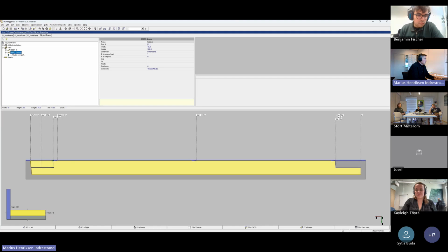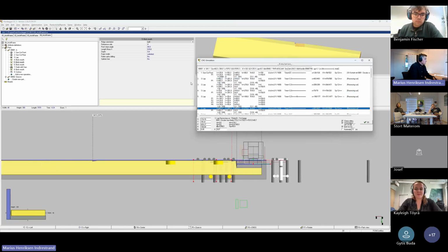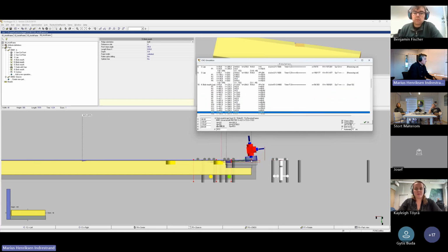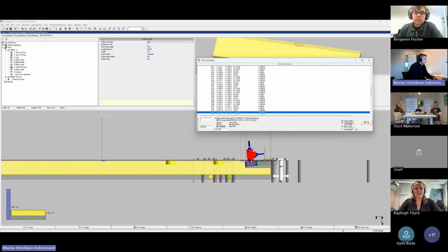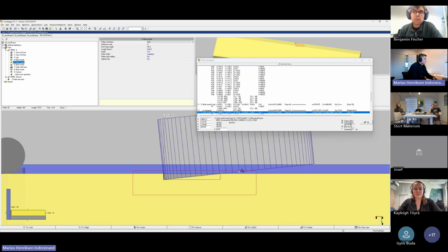There is also another thing to think about, and maybe you need to talk to the Hundegger operator or your QA guy, because the Hundegger will use a different tool. The V-cut will be exported as a bird's mouth. So for us, with our machine data at least, could I remove this top? But it will use the revolver. So it will take this cut with the revolver.